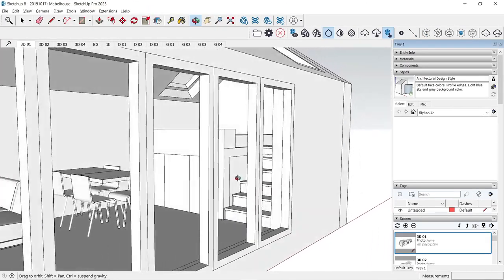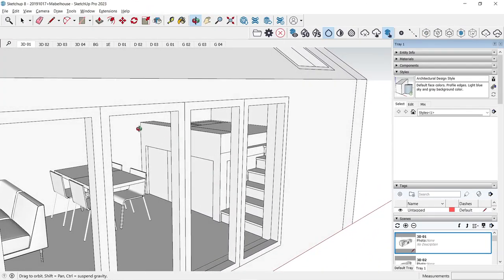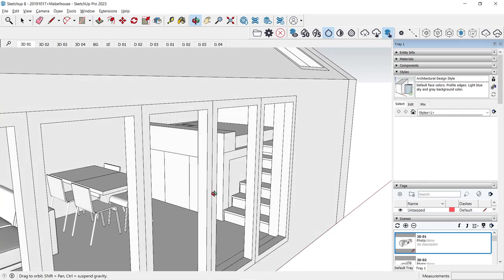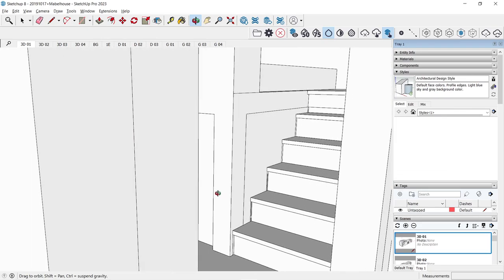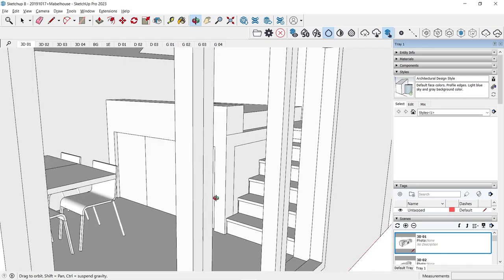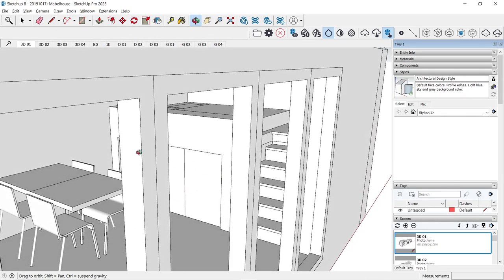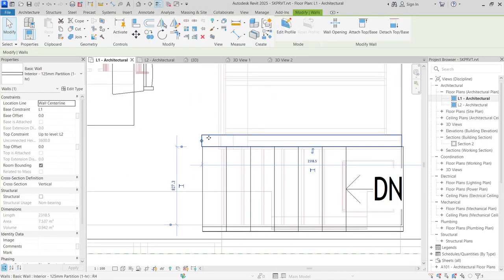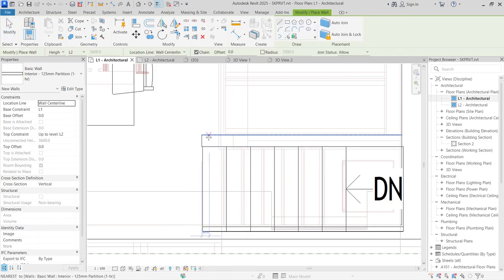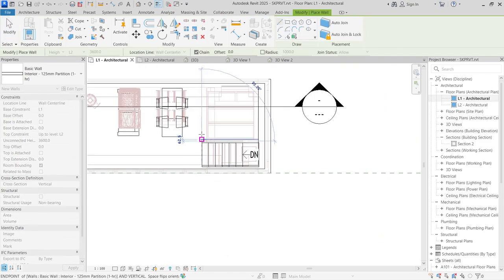So we see here that there's a structural wall here, or a wall, I'm going to call it, and I don't know what is inside the wall right now, but I know that there's one wall here which we have created, and then there's another wall on this other side. So we're just going to use the same create similar internal wall to create that. So inside of Revit, we can use this and say CS to create similar. You can join it to this point.